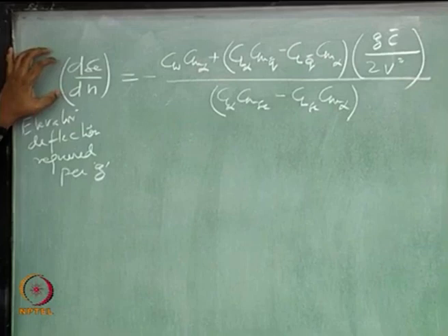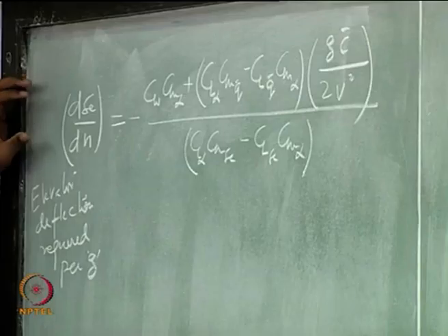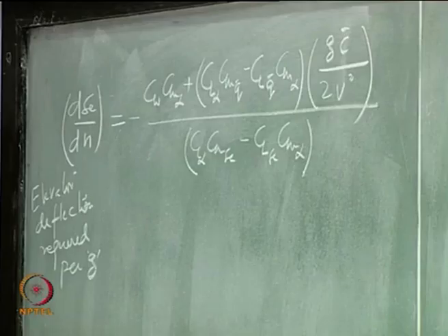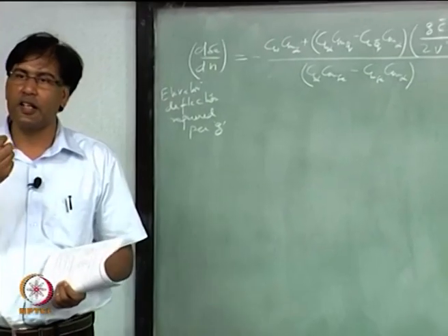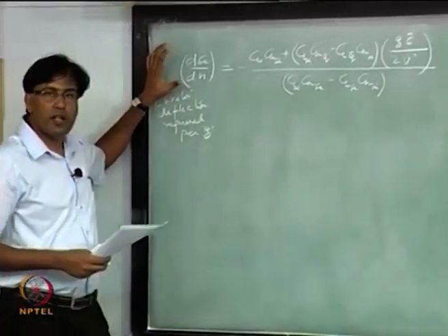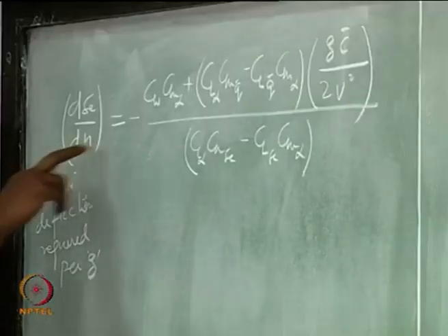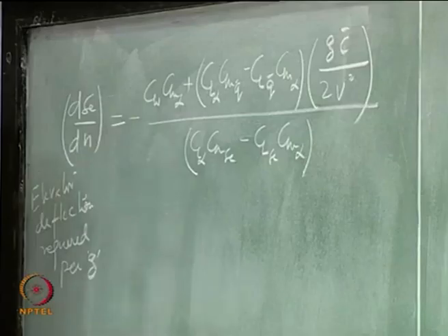Setting this to 0 will give you... what does it mean? Setting this to 0 means you can get a large acceleration even without deflecting the elevator, right. So the elevator becomes very sensitive, and any small deflection in the elevator can give you large normal acceleration, right. That is what a small value of this quantity means, and it is a function of the CG location.